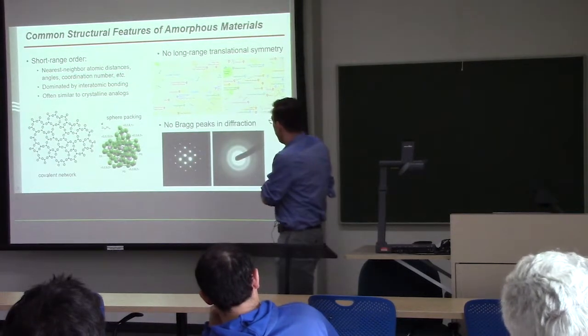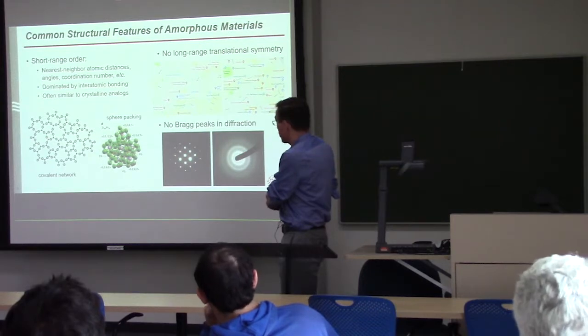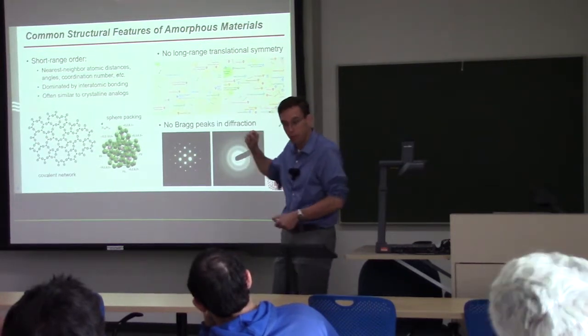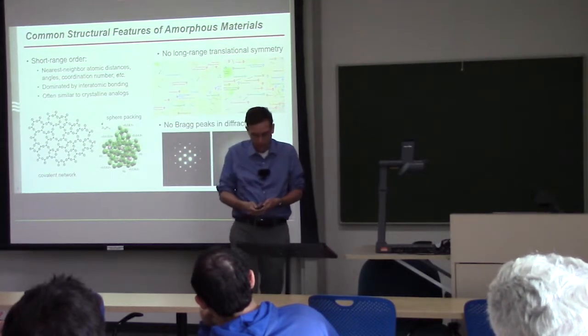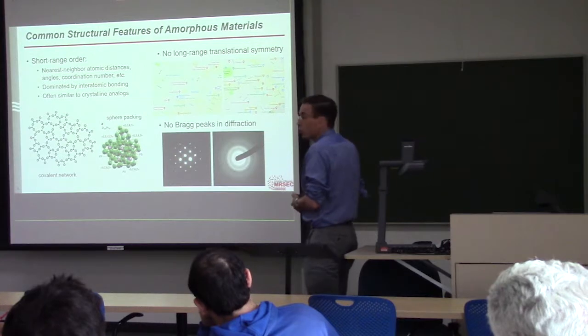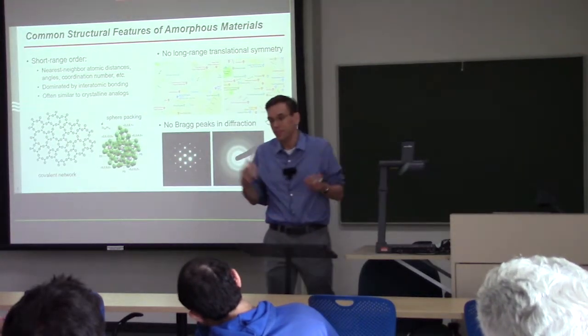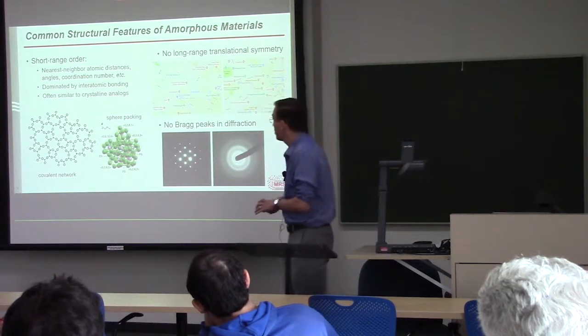In contrast, of course, a crystalline material, because it has long-range orientational and positional order, has this set of very well-established electron or X-ray reflections that are sharp and bright and isolated. You can learn about the structure by analyzing their intensity if you want to study single crystals. If you're looking for these kinds of ideas at any scale, you can do this. And so this is Paul's